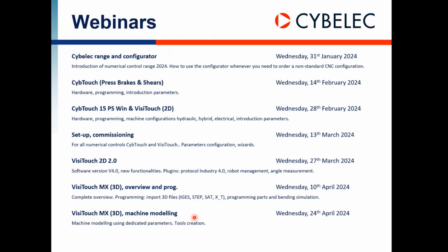And then the 2 final webinars will be regarding the VisiTouch MX, which is the high range controller with 3D. First webinar will be how to program and how to use the 3D on our controller. So program a part or import a 3D part, which can be STEP, IGES, or DXF files, for example, and how to select the tooling or do the automatic calculation, and how to basically use this software.